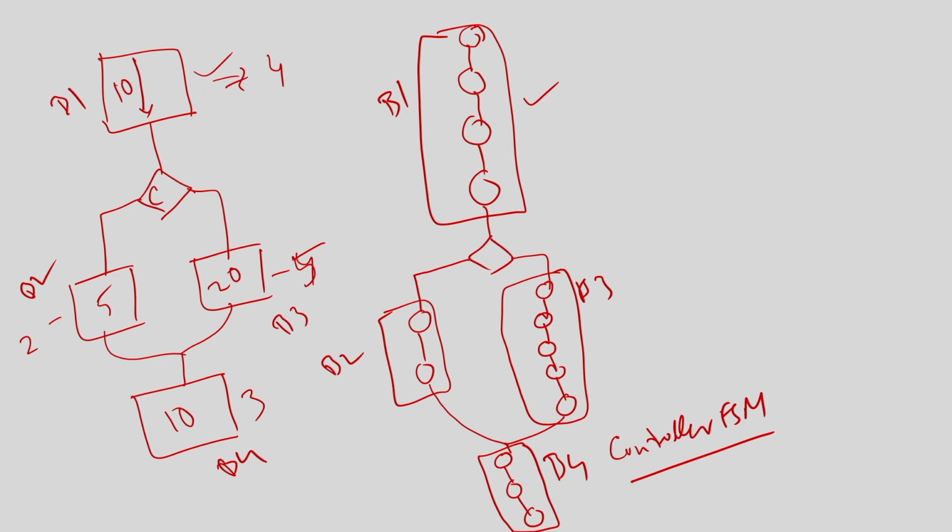In path based scheduling, we try to solve that problem. It tries to achieve minimum latency by sharing operations across basic blocks. So how does it take the code? Instead of taking the basic block, it now takes a path. How many paths are there? You have 2 paths.